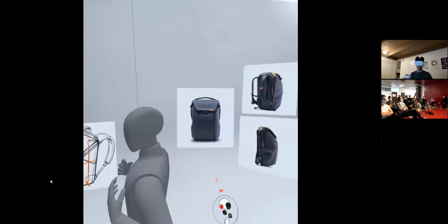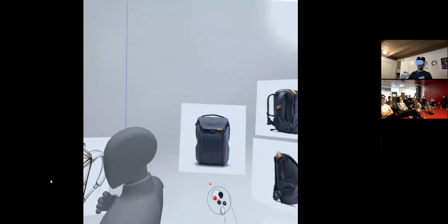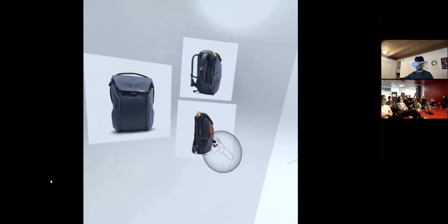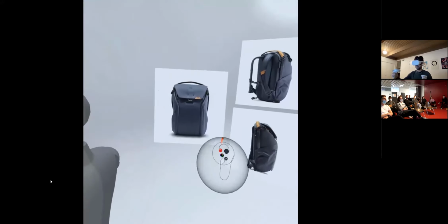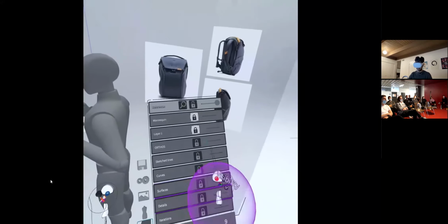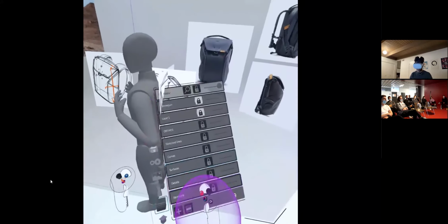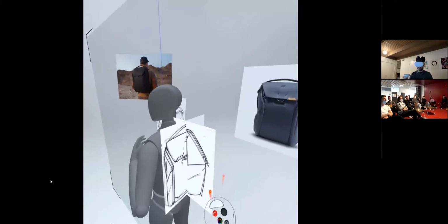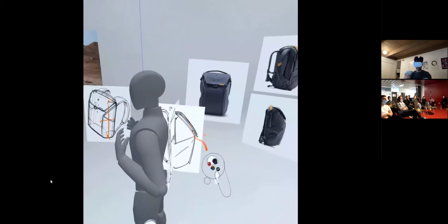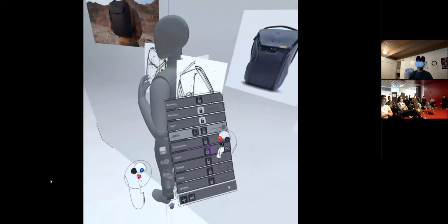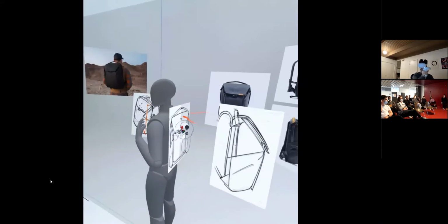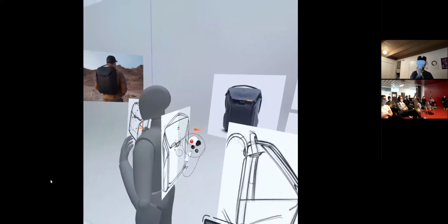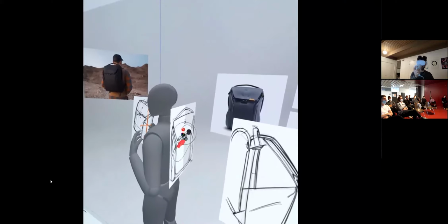The next thing I did was, like we talked about, I extrapolated two-dimensional views. So I already have the front view. I just needed to do that side view. So I sketched them next to each other to be able to get these. These are my orthographics, and these are going to drive my plan sketches that I use to get those 3D curves. So what I do is pull these, make sure that they snap, and pull them into, you can see that it definitely snaps into a planar view.